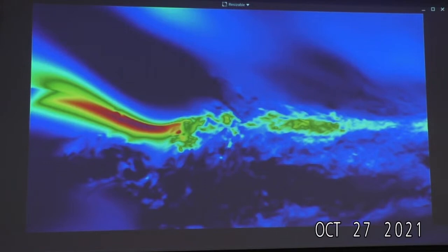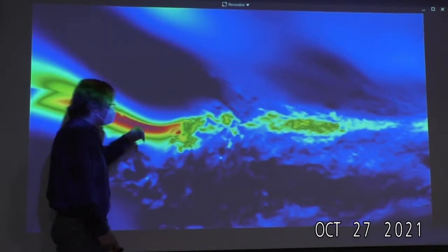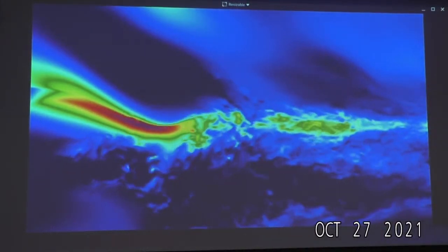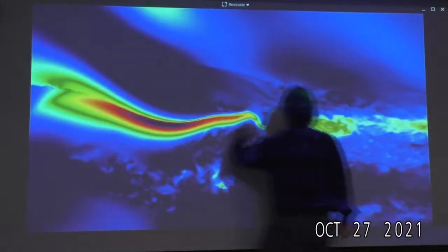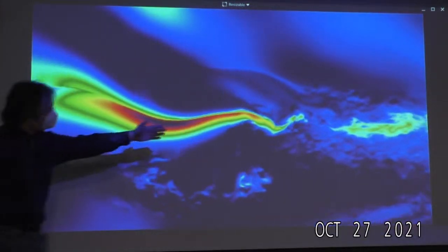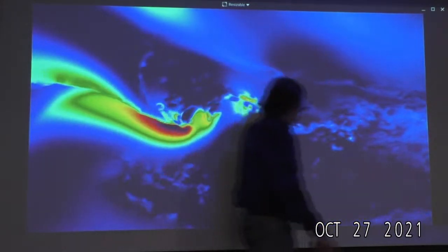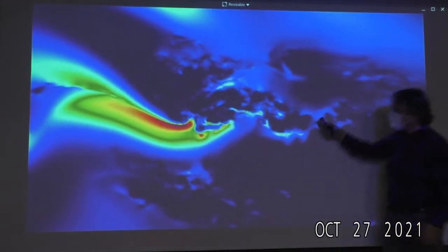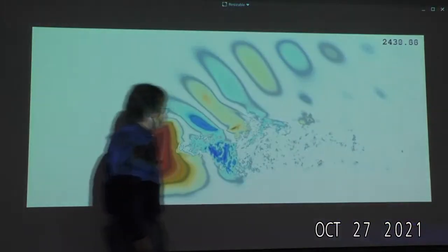So this is much earlier on. Okay, this is before the hydraulic jump forms. One thing I want you to focus on, this strip here is like 70 to 90 meters per second. There's kind of a pre-existing jet before the hydraulic jump forms. And then right when it breaks, I don't know cause and effect here, but once the jump forms, that's gone because of what a hydraulic jump is. You now have a much deeper region, a lot of turbulent stuff going on, and the flow is actually smaller.